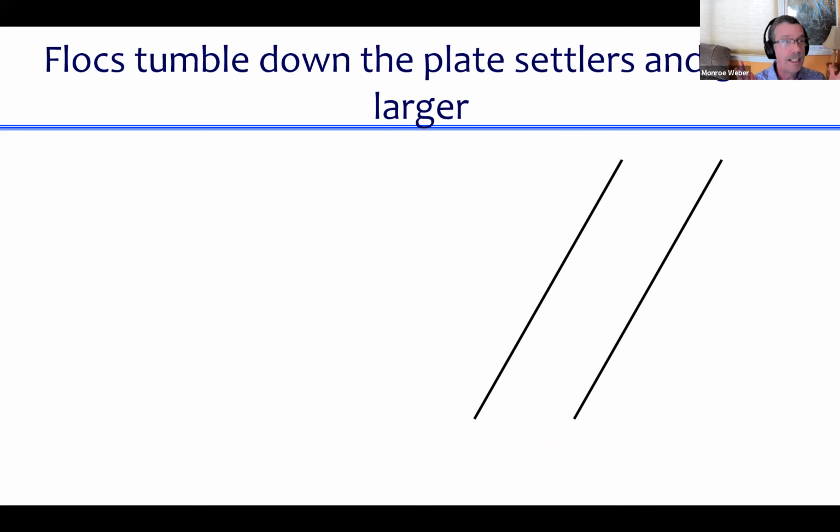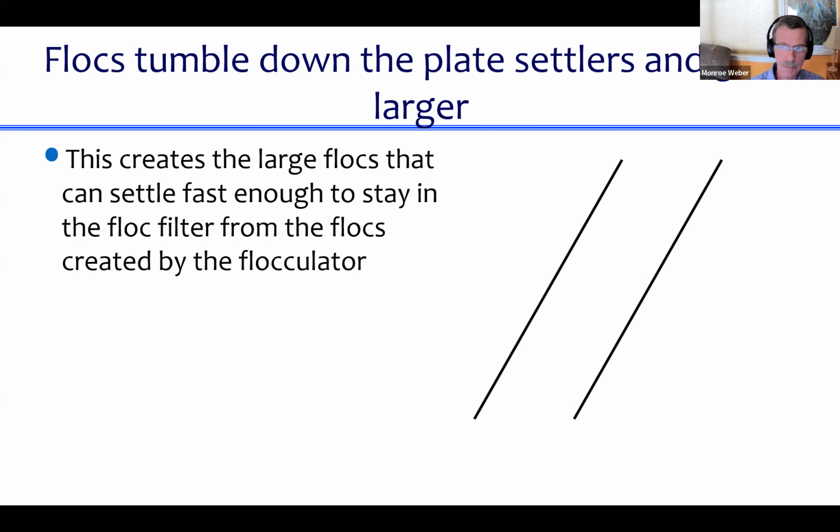Okay, so you saw it happen on Monroe's slides. A bunch of particles went up, they slid down, they formed an avalanche, they aggregated into a larger particle. That's how we get our blue guys. And this is cool. I think I didn't have this insight before putting together this set of notes, that I never knew how particles that are removed by a plate settler get to the bottom of a sedimentation tank. Did I talk about this on Tuesday?